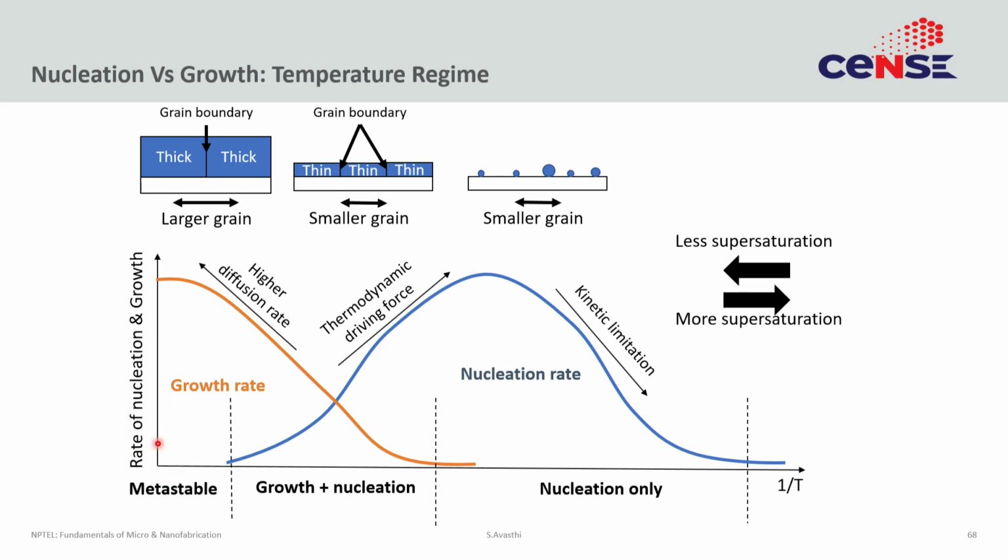It wants to nucleate, it wants to freeze, but it has not yet found a nuclei. Why? Because the nucleation rate is 0. You see, the nucleation rate has fallen. Now, because the nucleation rate is 0, the water has not started to freeze. And if the water has not started to freeze, even though there is a thermodynamic imperative for it to freeze, it is still waiting. So, that is the challenge.